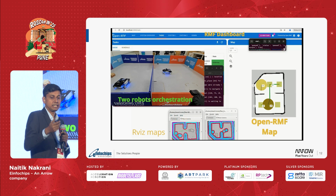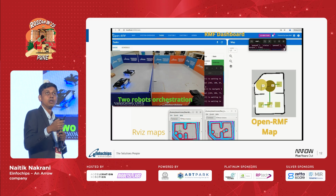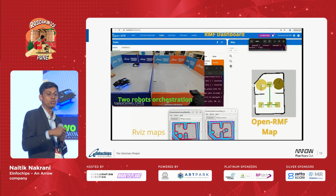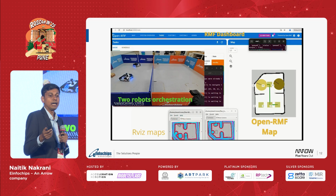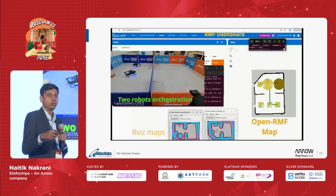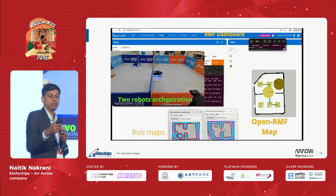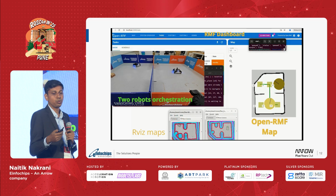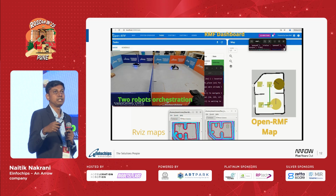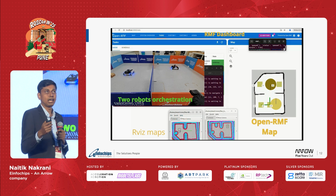So what we did is we created one common path in order to move both AMRs. We gave both AMRs continuous goals to move from one end to the opposite end. You can see that once the path is clear for one robot, then your second robot starts moving. So that's how OpenRMF traffic management comes into play. It takes care of your path, and it manages which AMR has to go first, and which has to wait for a certain time. This is called a negotiation between the tasks that OpenRMF does.